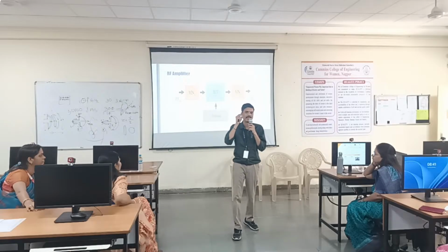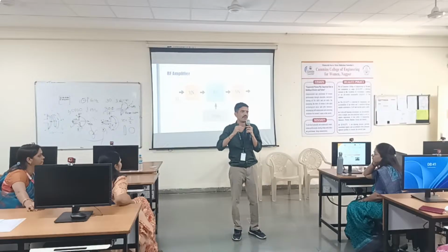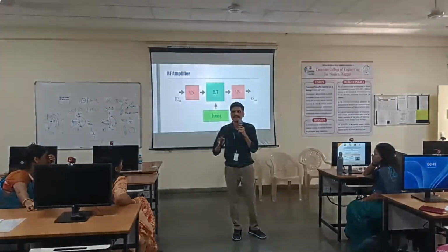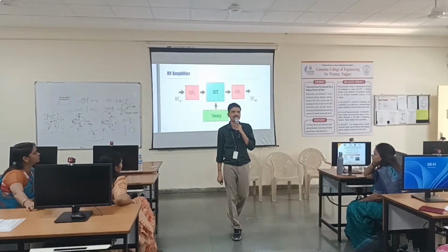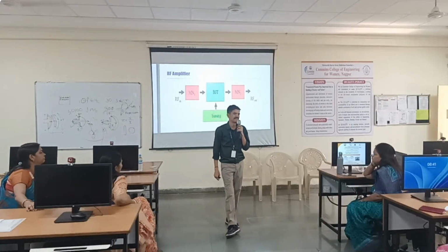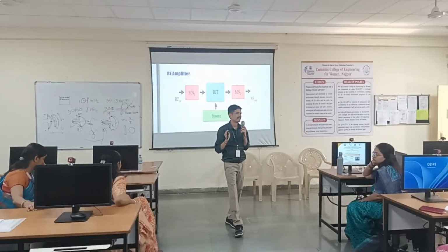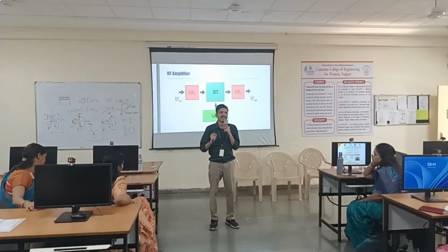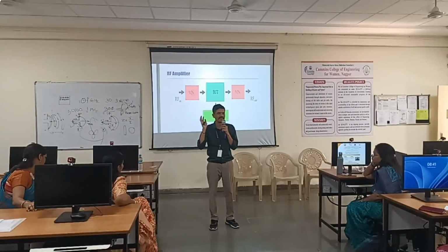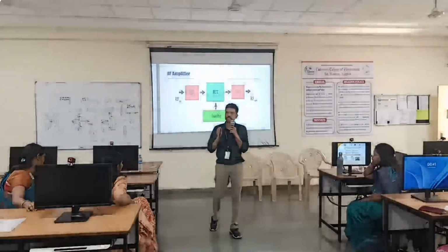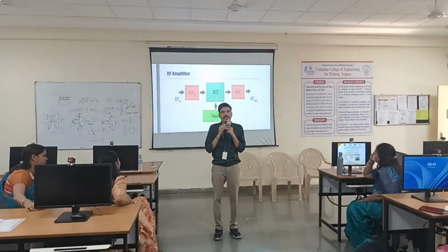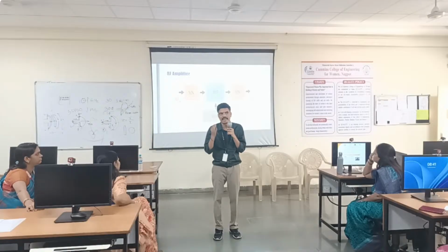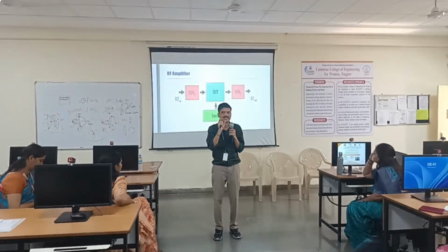That the PA you have made, how will it operate if you apply some complex modulated real world signal. Then the story starts for non-linearity. It's all about non-linearity. So just make a note of this word. PA design is handling non-linearity. You will appreciate why I am saying that PA design means handling non-linearity. If your amplifier goes into non-linearity, then only it will produce some good efficiency. You have to run into compression.